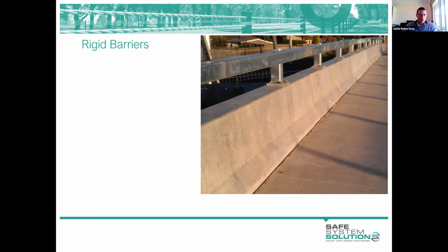So that lack of deflection is good in terms of maintenance requirements, because you typically don't need to attend to the barrier after it's been struck. It will incur little or no damage and it will stand to live another day. But we do see some more serious outcomes when crashes occur with these type of systems. And that's especially the case where higher impact angle crashes are possible with these barriers.